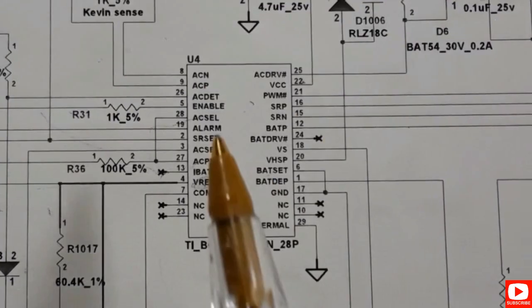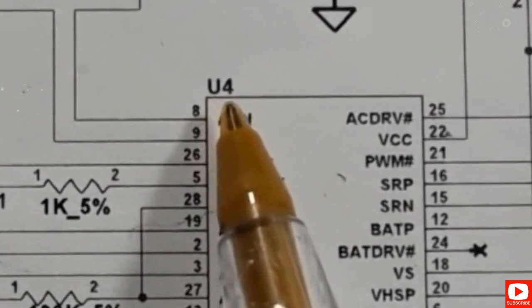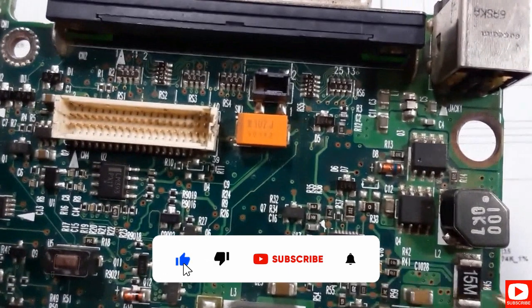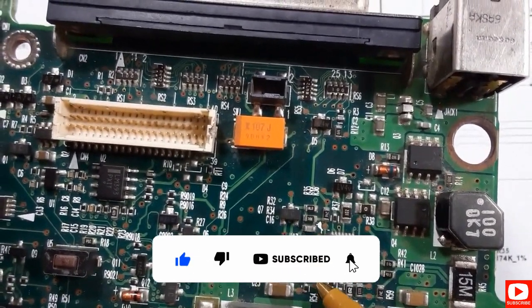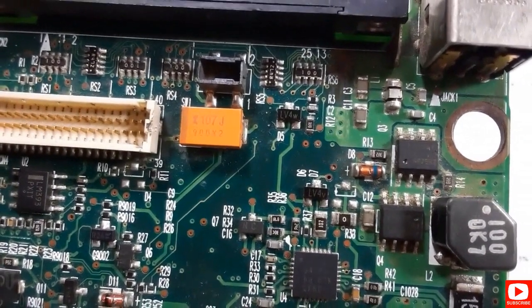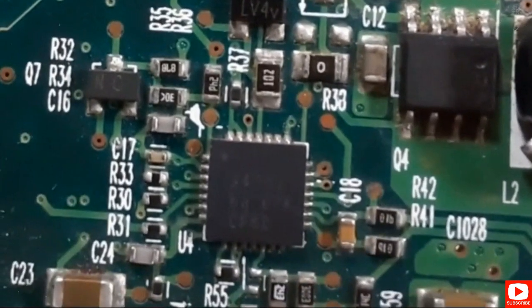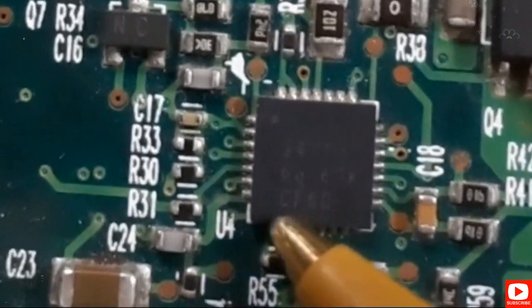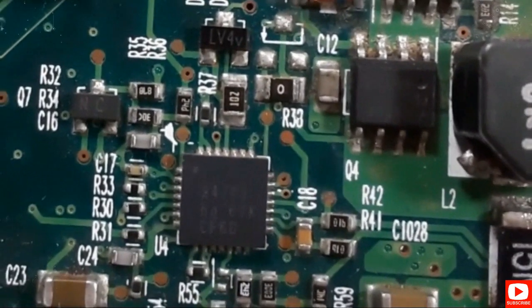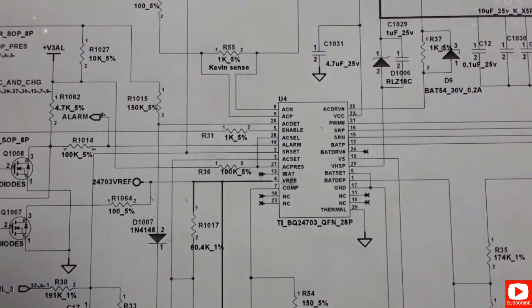Here we have this charge IC with the reference designator BQ24703. Here we have U4. Its reference in the motherboard is U4. So let's check it out. As you can see here in the motherboard, we have U4, the same reference as we have seen in the schematic. This is the power management IC, or the charge IC, for this motherboard. Basically, this IC is responsible for the power in the motherboard.